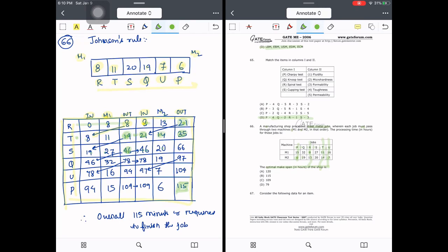First, using Johnson's rule, we created the sequence, and we created it in such a way that after machine 1 works, only then does machine 2 take the work. If machine 2 is busy in the meantime, then the end product of machine 1 has to wait for those particular hours, and once machine 2 is free, it will take the job. That is why there is a delay.